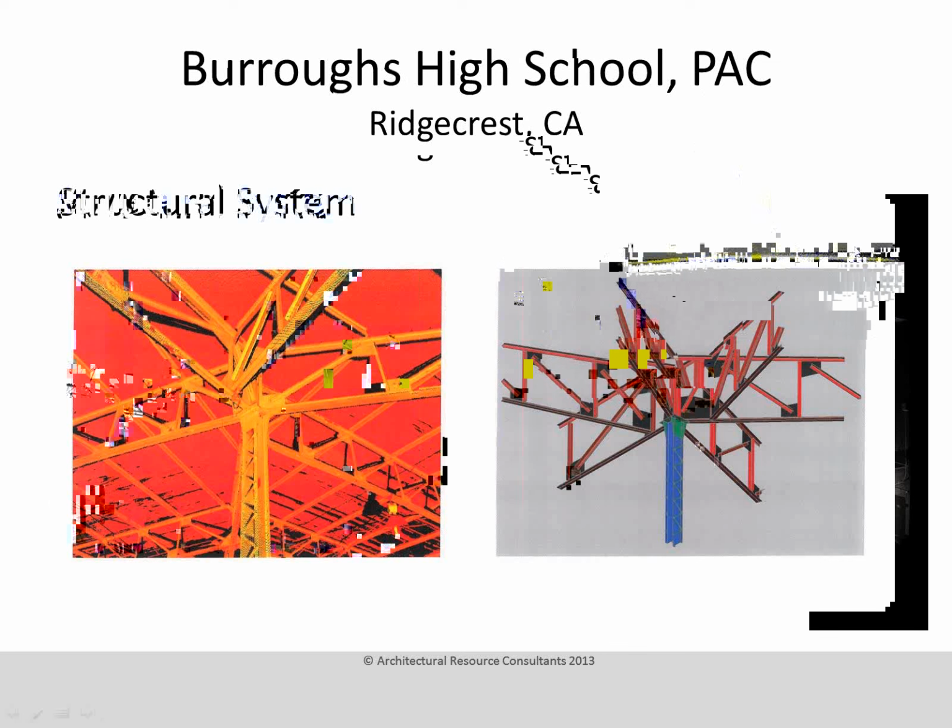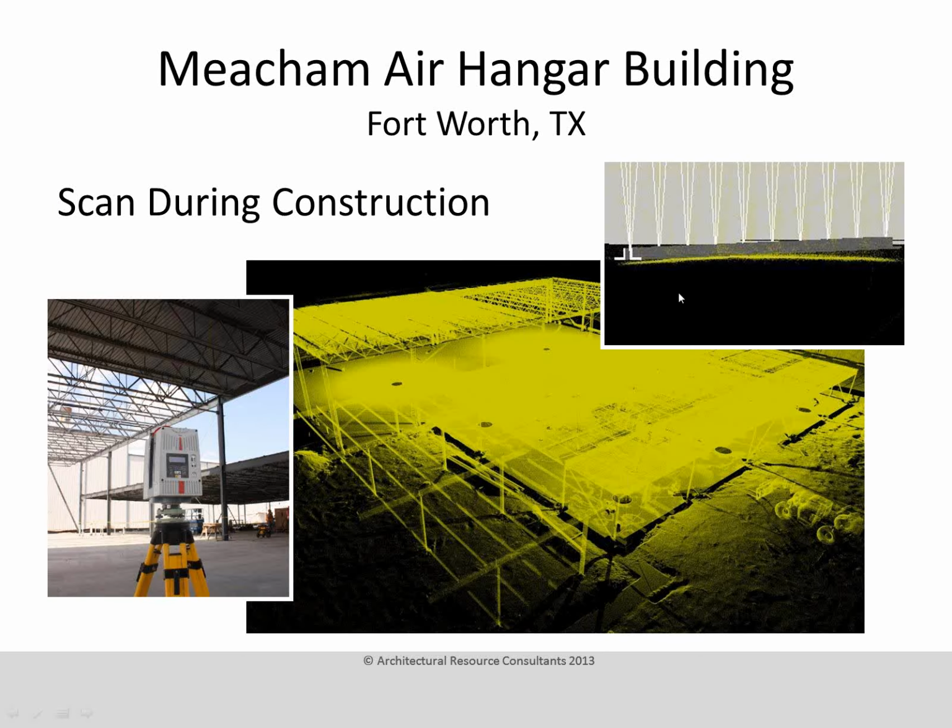A tool like Revit's going to want to draw this nice and straight, even though the actual joists are bent like this. Once that roof gets its load, it's going to flatten out and it's going to meet the design purpose. So if you're modeling from scan data, you're going to have to decide how you want to represent things. Are you going to try to model the real-world condition, or are you going to model a close approximation? These are all things that you don't generally have to deal with when you're doing what I'll call design BIM.